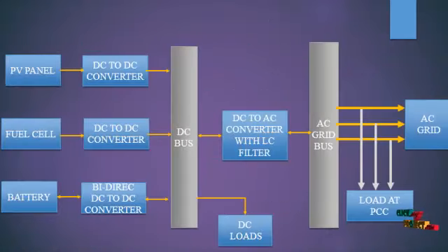Next we see the flow diagram of our product. This is our flow diagram. Generally, from a control point of view, photovoltaic generation units can be classified into standalone and grid connected configurations. Due to the intermittent nature of PV power, battery storage is employed as a critical element in PV standalone applications to maintain the power balance in the system and enable regulation of the load voltage. Islanded microgrids share the same issue with standalone systems, since the battery storage is needed to maintain the generation load balance and to regulate the microgrid voltage and frequency.